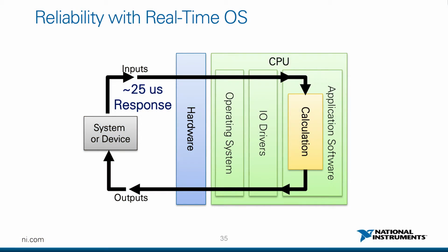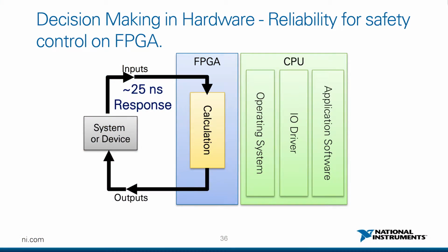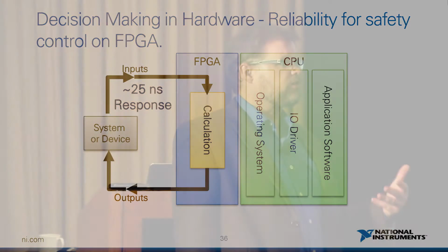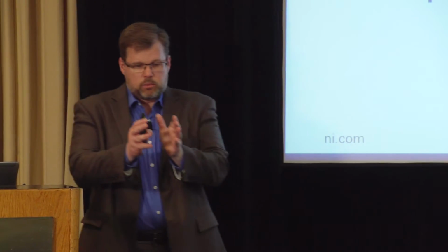And for those of you that are more graphical in nature, if we think about this, as I said, this 40 kilohertz control loop rate on a processor-based system, if you push that out to the FPGA or to that hardware implementation, you get a 40 megahertz control loop implementation, so a factor of 1,000 times faster.